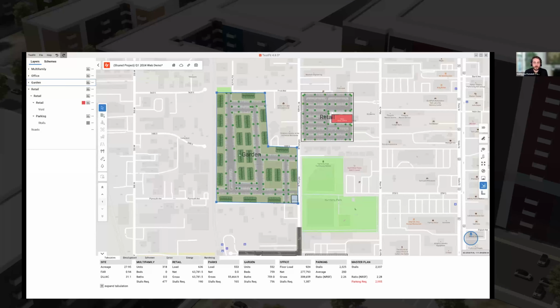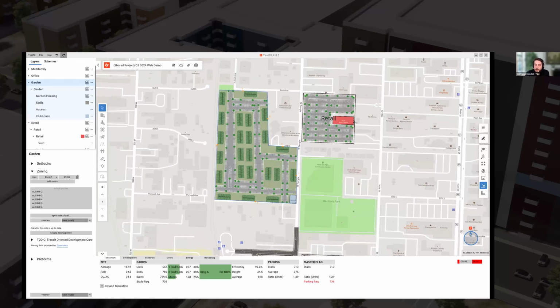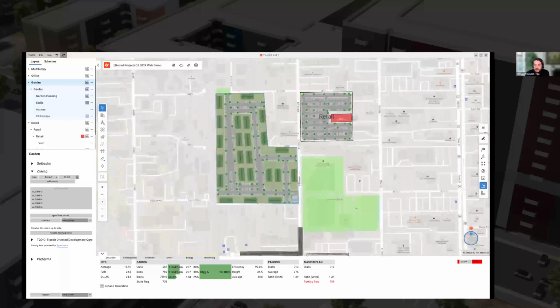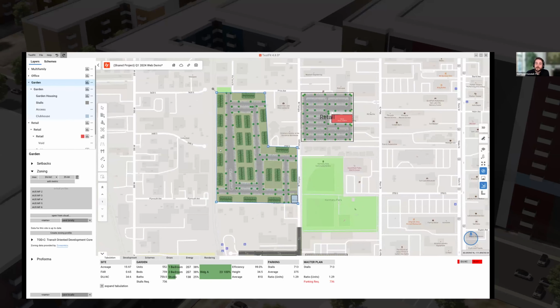Sometimes, let's say we're working on this garden site, we might not be using true north to define or work on this project. So now what we can do is, on this lower side over here, I can left click, and that's going to rotate the view that we're looking at. But if I right click over here, I can set my project north. So let's say for this project, I want this to be the lower portion.